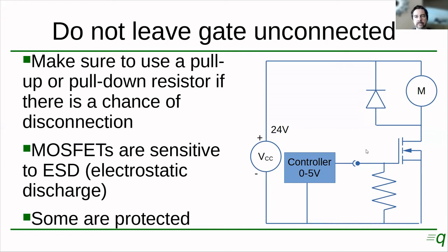Discrete MOSFETs are not. So be careful when handling MOSFETs that are not already installed in a circuit, because those are very sensitive to electrostatic discharge. So make sure you ground yourself and you discharge any static electricity that you may have.